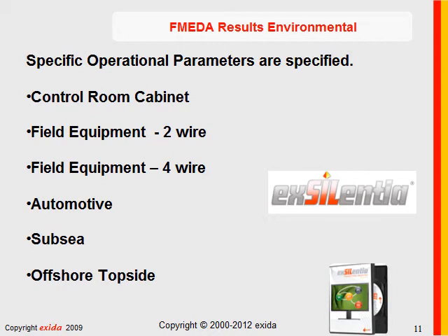What happens if you have a brand new product, a brand new design? By the time you get field failure data, the product may very well be out of production. So how do you get data for a new product? Answer, FMEDA. So thanks for the question. My answer is FMEDA is a combination of all the known information. The operating environment, the design characteristics of a product, and field operating experience. And in our case, 10 billion hours.